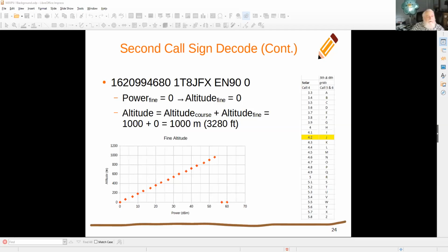By that same token, Jim was talking about channels, but the overall total WSPR channel on any band is 200 hertz, because each WSPR channel only requires 6 hertz of bandwidth. As a result, you only have 33 channels that you can transmit on a 200 hertz bandwidth, and that's why we use 30 channels, and that's why we can decode that with 3 different prefixes of the phony call sign.